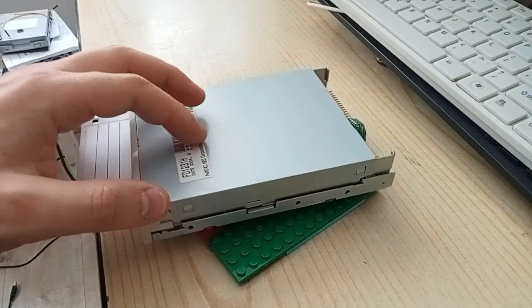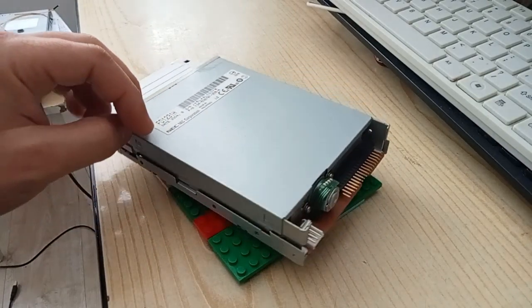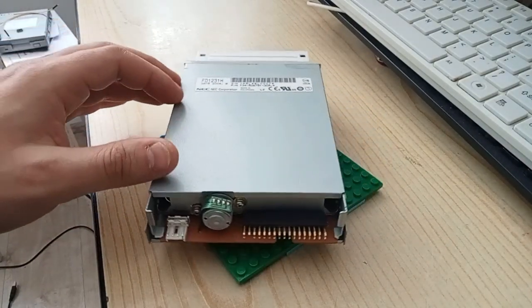A bunch of 4E sync bytes, a bunch of 00 sync bytes, and signature C2 C2 C2 FC. Next there are sectors. Each sector is constructed from a header and data. Sector header first: a bunch of 4E sync bytes, a bunch of 00 sync bytes, then there is signature A1 A1 A1 FE, then 4 bytes of sector header, and at the end 2 bytes of cyclic redundancy check calculated from the signature and header.